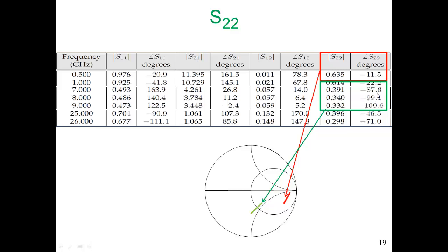The angle now is close to minus 90 degrees, where in this region here we really are seeing something that is close to being a capacitor, but it does have a resistive component, and if we follow this line in, bingo, we come to 50 ohms. So the manufacturer has gone to a lot of trouble to try and make it easier to do design so that we do not need very significant input and output matching in order to get this device to work.